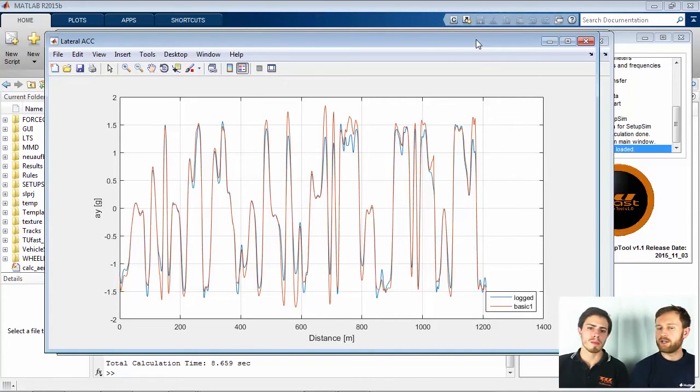Okay, so what is your decision criteria? So you say you have some log data, you're modeling a car. So when are you satisfied? We feed some parameters where we are not so sure if they're right, so that both of the curves have a delta of about 5% or less. Okay, great. This shows me that your validation is very important. And doing a parameter study on a car that is wrong, that is not representing the reality, does not make any sense. So for me, it seems like a clever first step to validate logged versus simulated data.